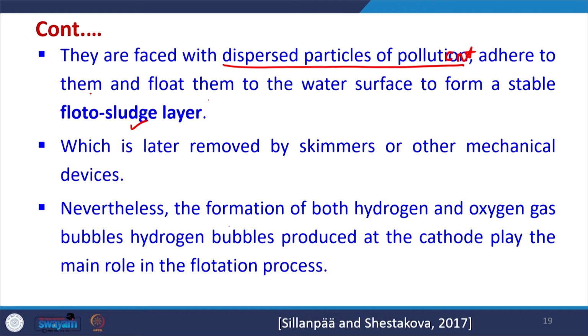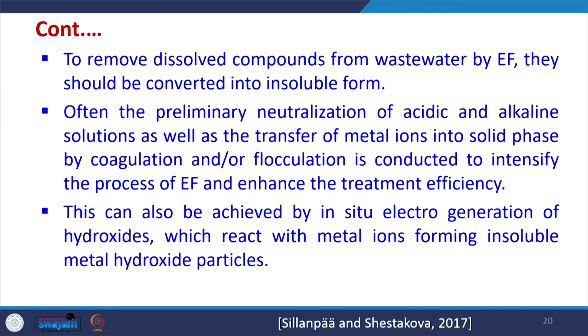The formation of both hydrogen and oxygen gas bubbles, produced at the cathode or anode, plays the main role in the flotation process. To remove dissolved compounds from wastewater by electro-flotation, they should be converted into insoluble form. So, any dissolved compounds present in the water, if you want to float them, should be converted into insoluble form.